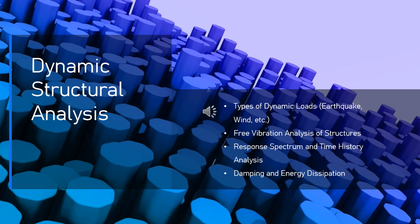Wind analysis methods. Building aerodynamics. Modern wind engineering uses wind tunnel testing and computational fluid dynamics, CFD, simulations to study how buildings interact with wind. Wind load calculation. Codes such as ASCE 7 or Eurocode 1 provide guidelines on calculating wind loads based on factors such as building height, shape, location, and exposure to wind.